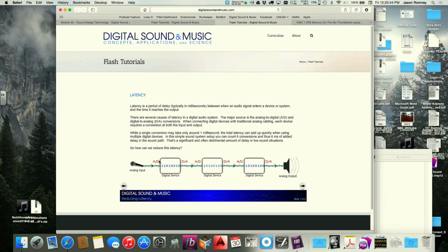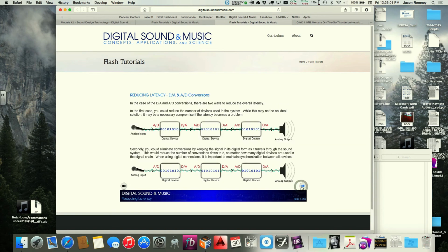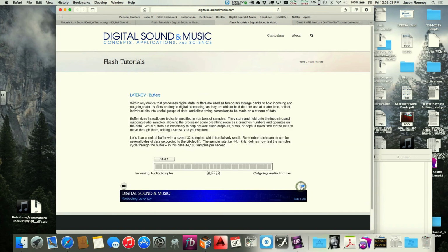Theoretically, you get a millisecond here, so that's 1. You get another one there, 2, 3, 4, 5, 6. You get potentially 6 milliseconds of latency in this system from the mic to when the sound comes out of the loudspeaker. There might be more internally that you are introduced to with some buffers and things. So one way to reduce that is to, oops.